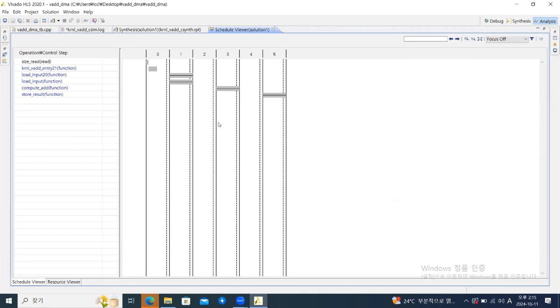So the benefits of using DMA. First, our IP does not have to compute unnecessarily, like addresses and incremental pointers and so on. The only thing we should care about is whether this is the last element or not. And secondly, because we have a bunch of FIFOs in our hardware design, it's actually fast.